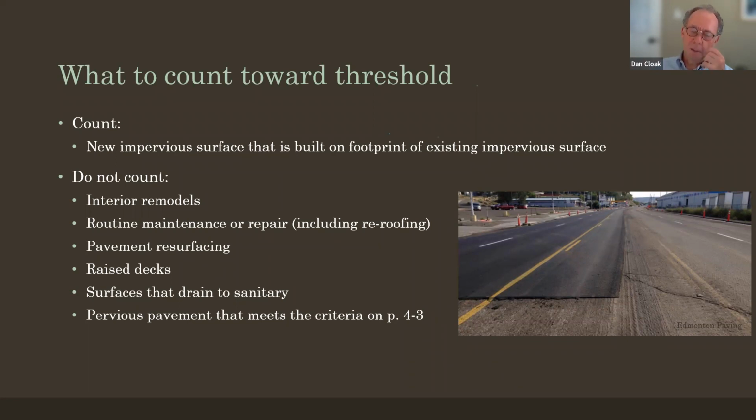And so if you have a project on an existing lot where an additional single family home is being built, it would not be covered if it didn't create or replace 2,500 square feet. If it creates 2,500 square feet and up, then it would come under the small project requirement.